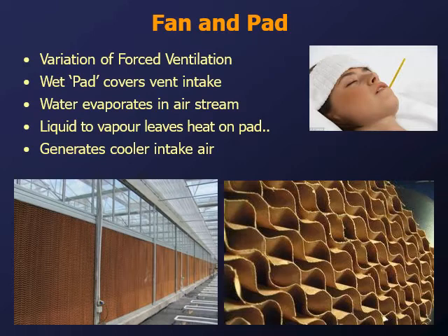But essentially, what happens is you have a wet pad. This is a close up. It's basically like cardboard, kind of a convoluted structure. And water trickles through all the fibers, so it's soaking wet. And then air blows through the holes, picks up the moisture, and in the process cools. Just like the wet cloth on the forehead scenario.